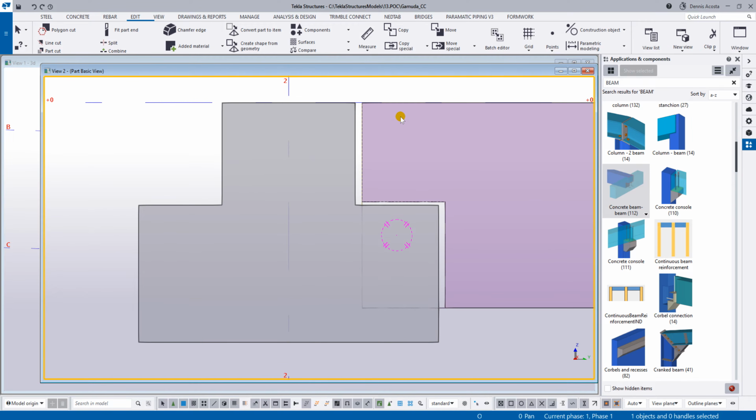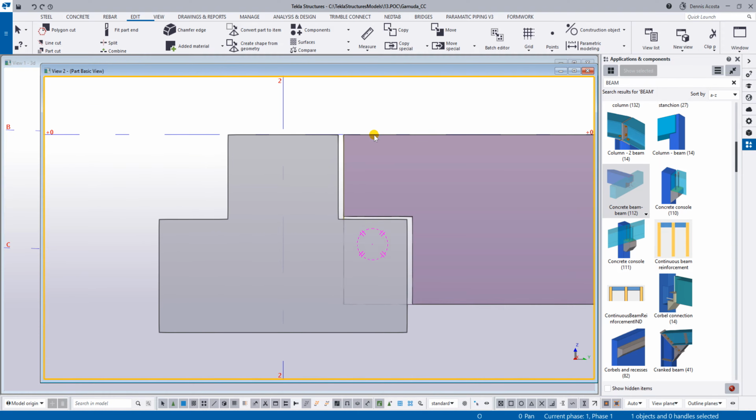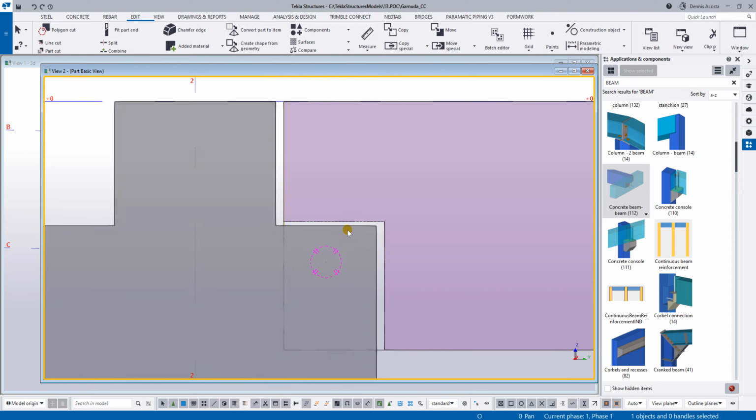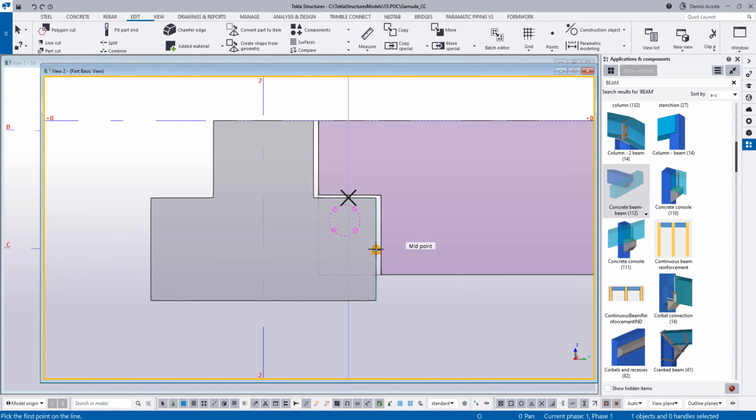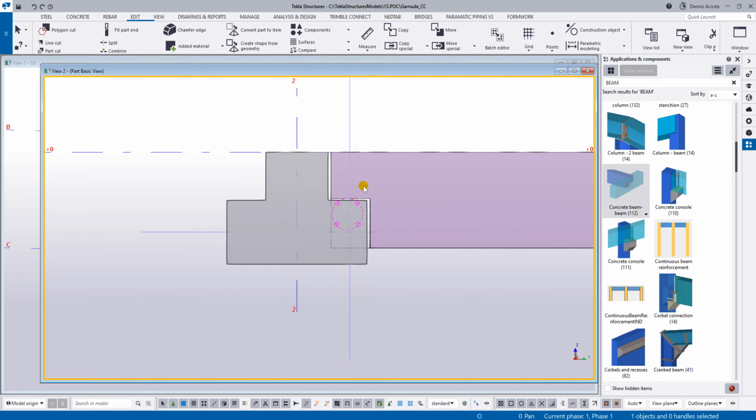Now, if I want to, I can also create a dowel here, a dowel bar. For the dowel bar here, maybe what I will do is I'm going to use a construction line. So from here, point, and then maybe 100. If that one is 230, anyway, this one can be changed, maybe 120, all right? And then another dowel here, maybe center of this. So that one is the shape of my dowel. I use the construction line, all right?